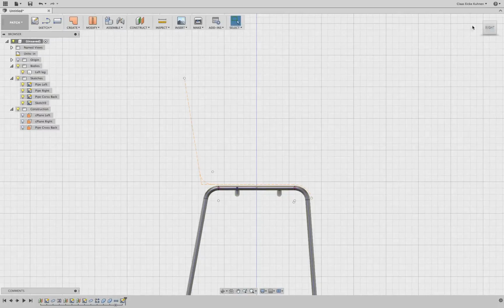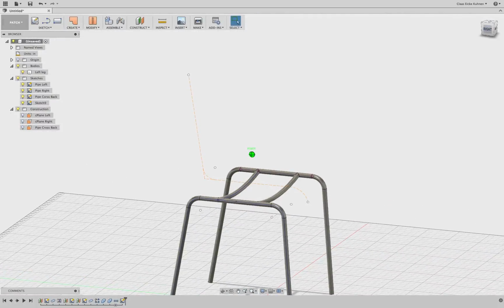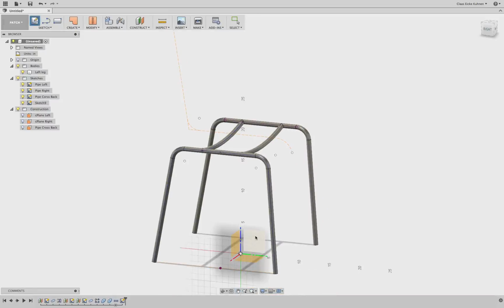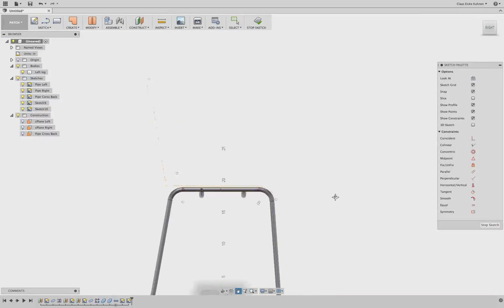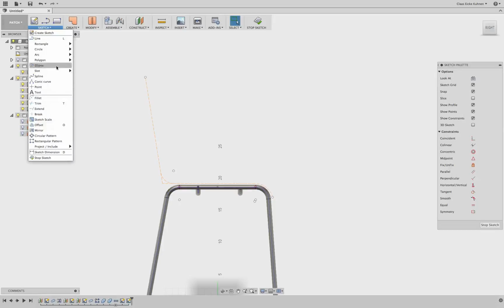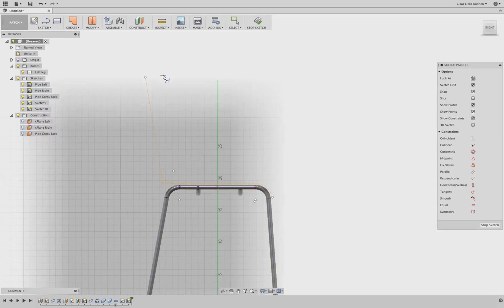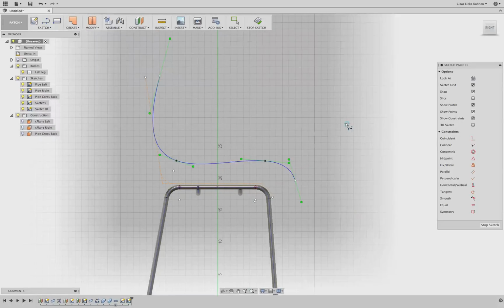Because now I will create a new sketch. Also on here, there. And then I will introduce you now to the spline tool in addition. That's a pretty nice tool. So spline tool, click, click, click, and click, can create some really interesting and fluid shapes. And you see how this one flows. So 1, 2, 3, 4 points.